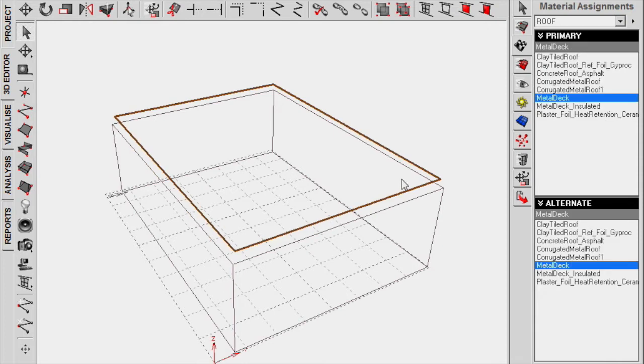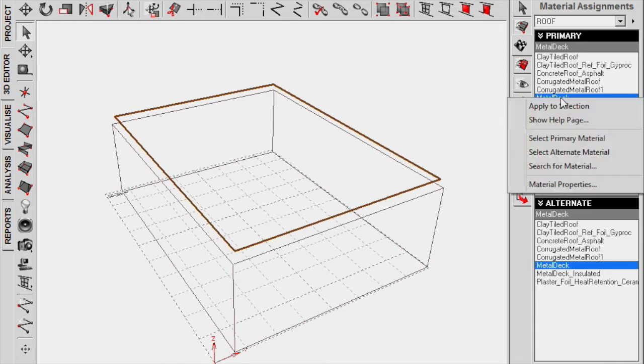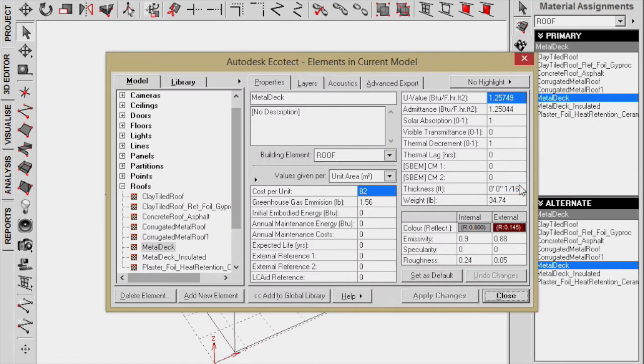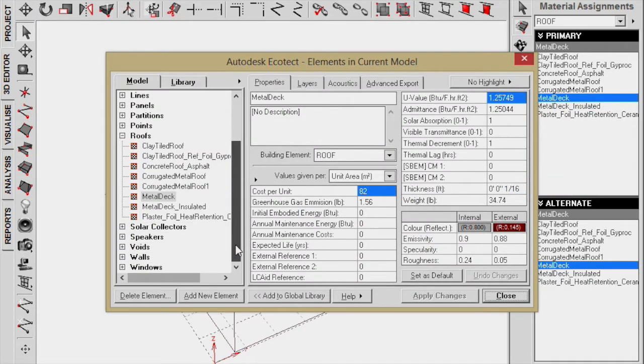We can also take a look at the roof. Don't forget the roof. Right now, the roof is made out of just metal deck, uninsulated. Notice it has an incredibly high U value right now, 1.25. Again, if we put some sort of roof insulation in there to lower that, we could really lower things. So, does anyone know offhand what amount of roof insulation you're supposed to put in for this area? Via Title 24 standards, if you're going to do a house here in Northern California, on the Stanford campus, something like that, you're basically going for an R30 kind of roof construction.